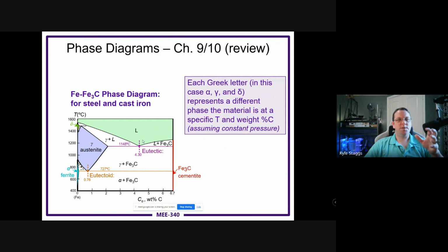Each of those phase envelopes is going to be different for every different type of material. Whether it's steel, whether it's aluminum, there are all kinds of different phase diagrams. This is also only a small portion of the iron carbide phase diagram. As you increase carbon, you change lots of properties, but for a lot of things, we focus on just this small section of the graph. So at higher temperatures, everything's liquid. Does anyone remember offhand what the eutectic definition actually is, or why it's significant?